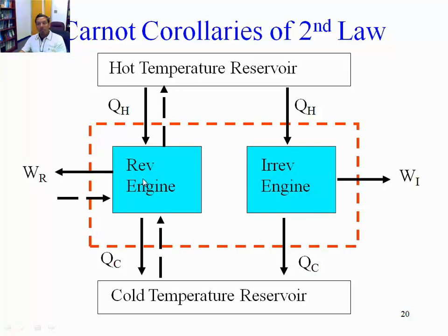And this is producing some reversible amount of work. And there's exchange of energy with a hot temperature reservoir, we call it QH, essentially Q in. And there is exchange of energy with a cold temperature reservoir, we call it QC, which is essentially Q out. It produces a net amount of work, which is essentially QH minus QC due to the first law of thermodynamics,